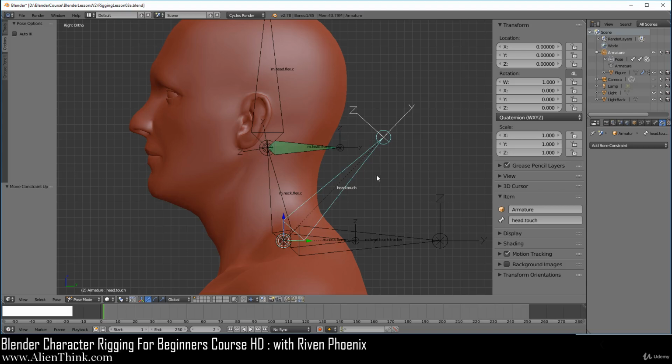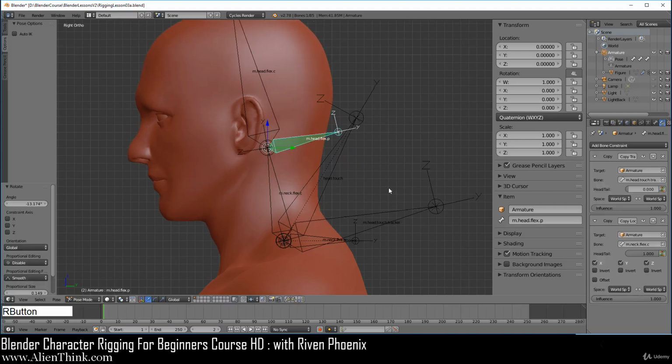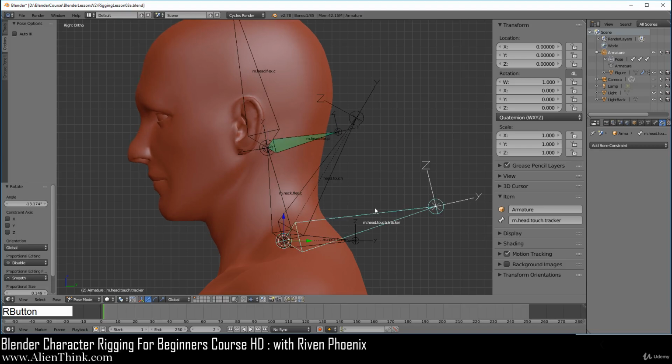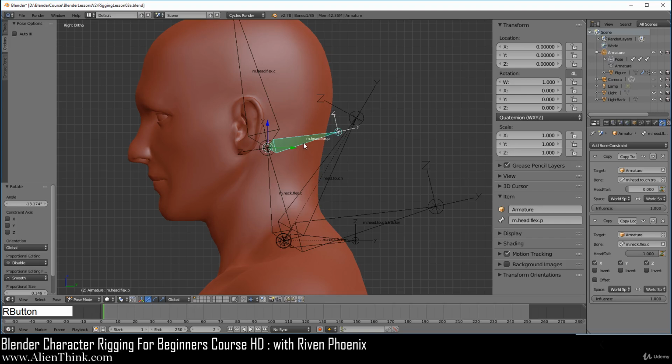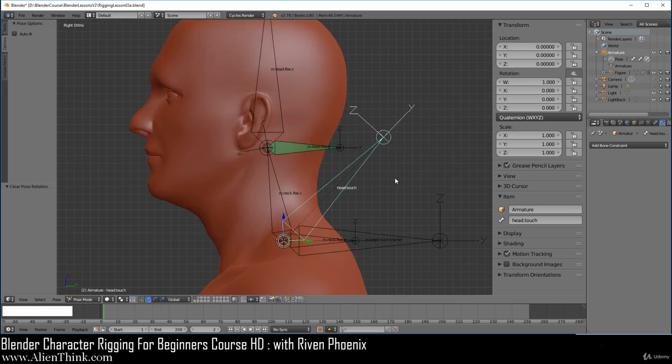Now take a look at what's going on. If we press the R key, okay, notice that this bone is perfectly aligned with this bone. Okay, so now if you click over here and turn off location, you can actually see the proof of this. Both of these bones are aligned. Okay, so here we're using parent-child relationships and taking advantage of the alignment to create this module system. So go ahead and click on this bone, do Alt-R to reset the rotation.